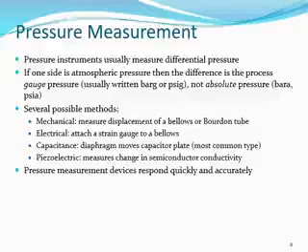For example, if one side is atmospheric, then the difference is the process gauge pressure. If one side is atmospheric pressure, meaning a known pressure, then the difference between them is the gauge pressure, and usually it's written as bar G or psi G. One is known, for example atmospheric, and the other one is the gauge pressure. Of course not absolute. The absolute pressure is the total: gauge pressure plus atmospheric pressure is absolute pressure, we can say that.